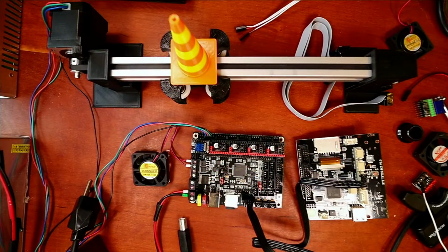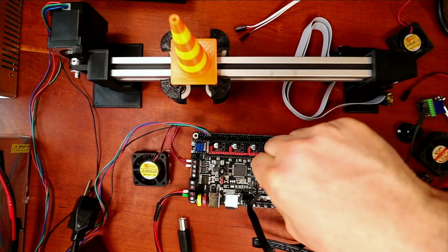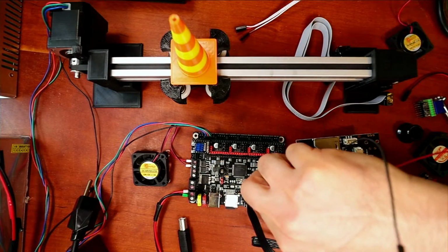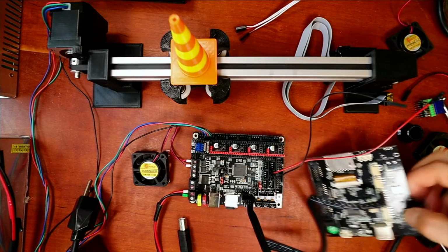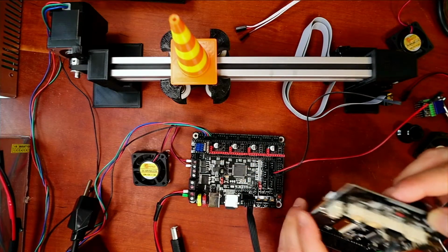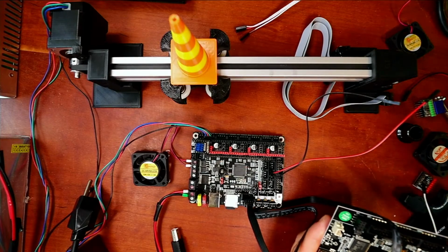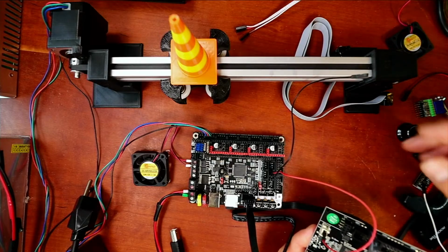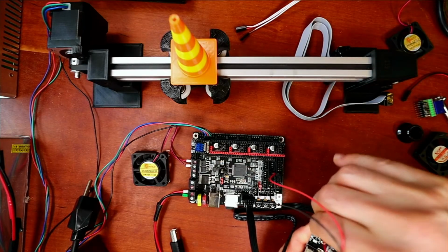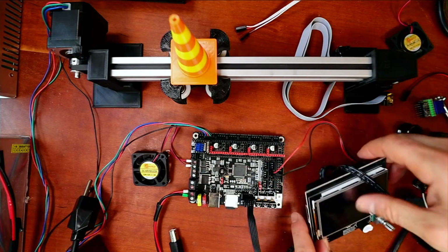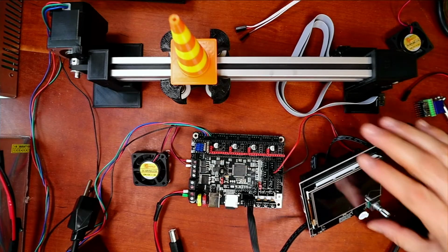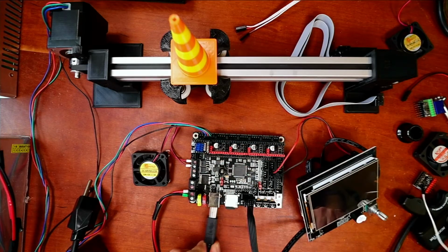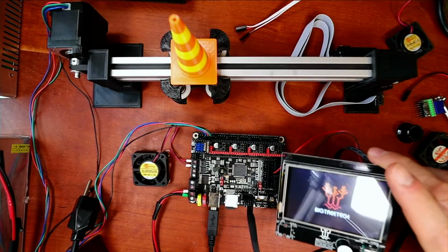So on here, I'm going to connect the voltage. I'm going to connect the ground. Then I'm going to go over to this board, and I'm going to connect the voltage and the ground. So voltage right here, then ground. In theory, this should power up if it's okay. If it's not, it's broken. So I'm going to move this jumper over for voltage off the USB. It does work.